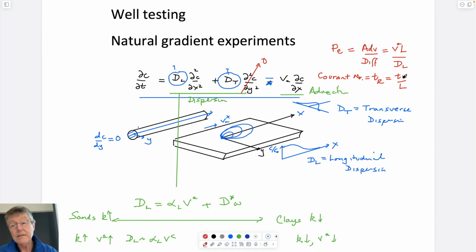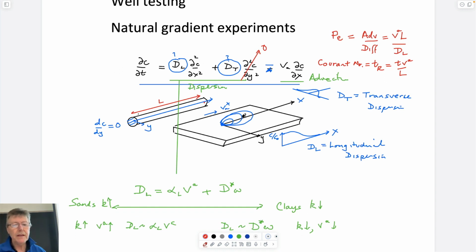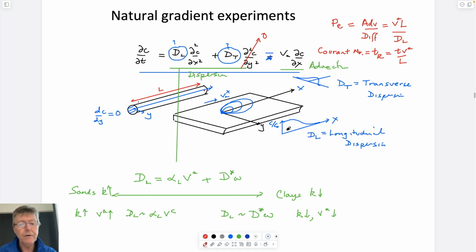So this describes how advection dominated, actually no, it just describes a pore volume. As you fill up the core, it goes from 0 to 1. As it reaches the end of the core at length L, it's exactly equal to 1. In both cases these are the advective velocities, and so we could replace these terms with those. We need to use a dispersive component. We define that according to this, which includes mechanical dispersion and molecular diffusion in these two parts.